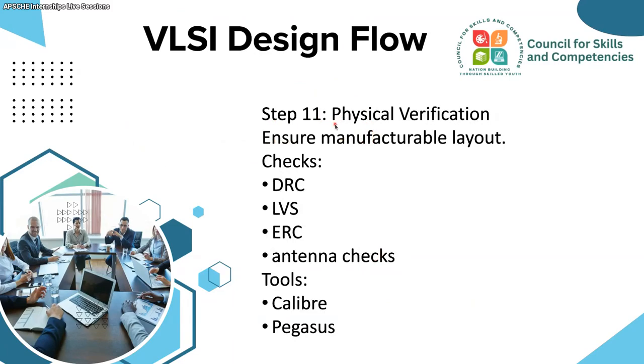In step 11, actual physical verification comes, using DRC check, LVS, and ERC checks, and then they will check for antennas, and then they will use tools like Calibre and Pegasus. That is what comes under physical verification.